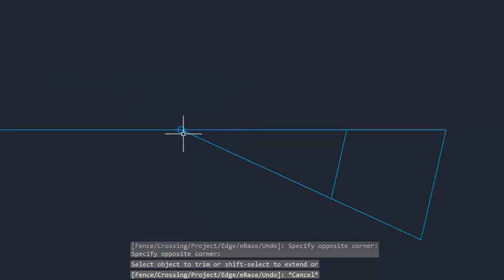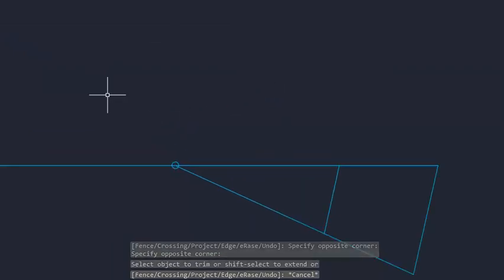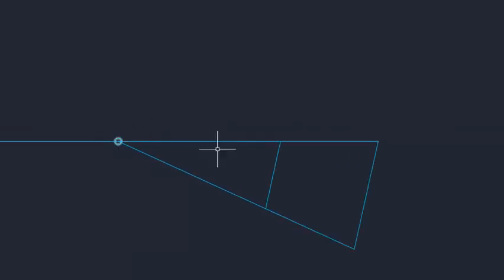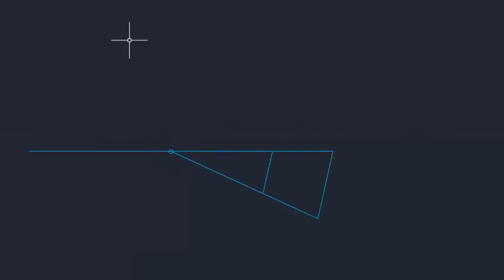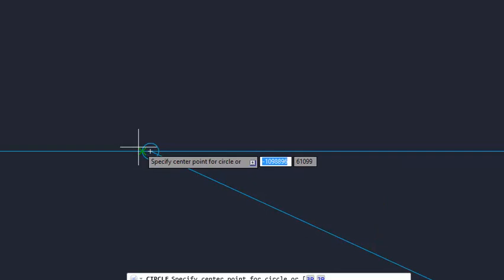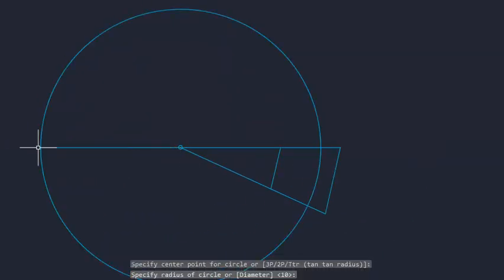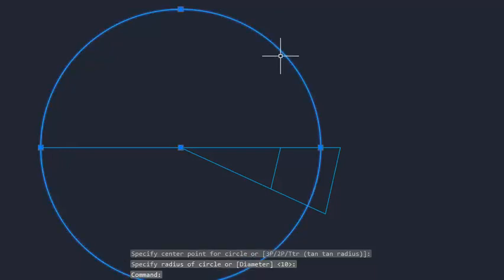Now since it is given, this middle part is going to be the side AD of the triangle. Remember, this one is already 5. So I stand here at this point, stretch up to the other end point, and draw an arc. This arc is already at 70 because we first measured off that.